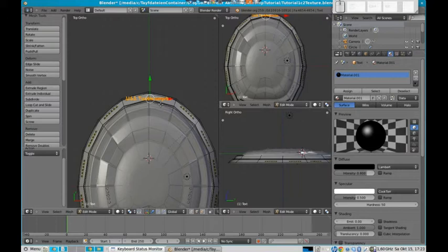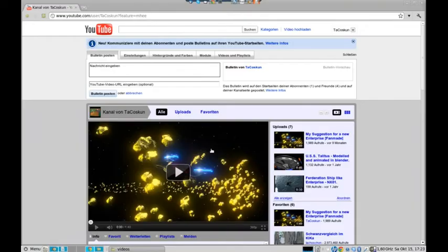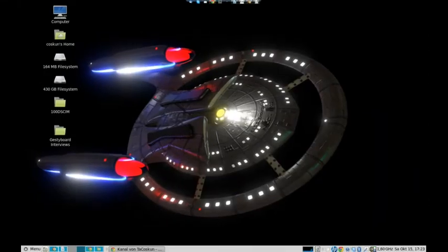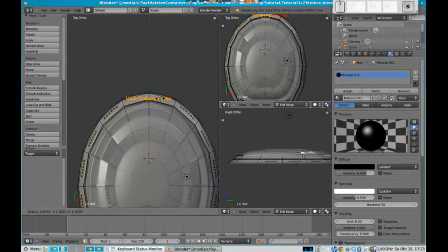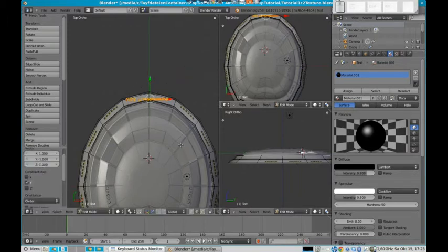But another problem here right now is that the text points to the wrong direction. You know, if we look for that, for example, to this file here, we see that the label is directed to the other direction. So, still not correct here. So let's mirror it according to the y-axis. So let's scale it by the y-axis with the value -1. So we mirrored it actually. And if we then press Shift W and adjust the size, it should look already correct.